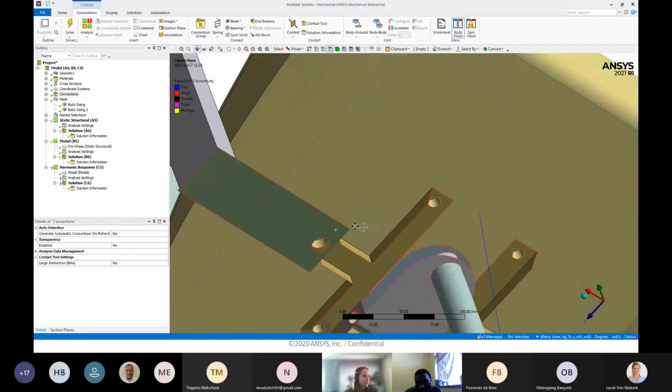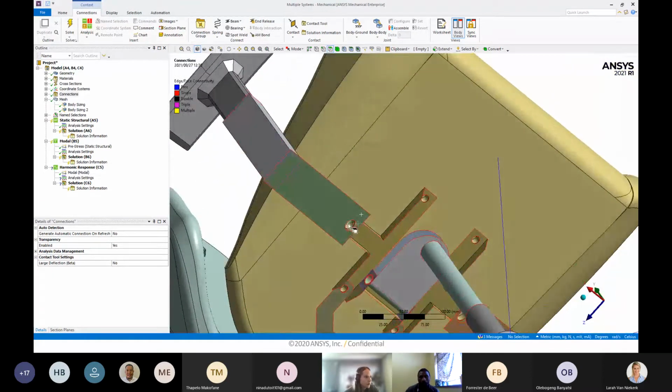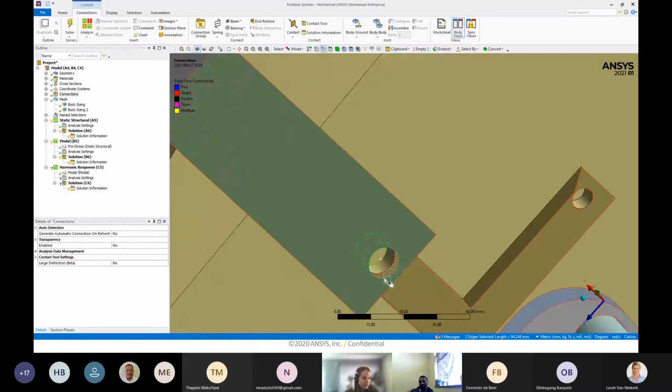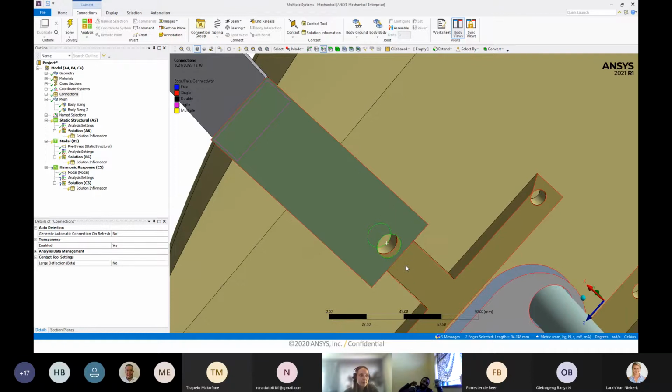I've made this mistake as well. What people will then do is scope a beam connection from this outer edge, or if there's a washer face, you can also do that, to the inner one without taking into consideration this middle edge. In this case, the middle edge will still be free to move around because your beam connection doesn't have any nodes